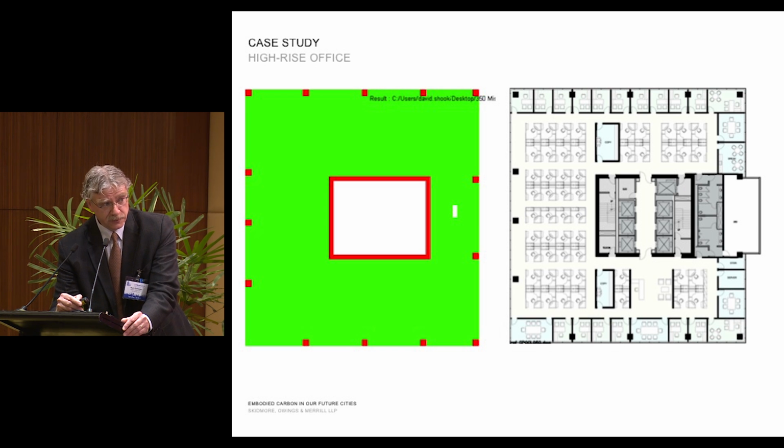It's a core-only building. We optimized the floor, and the red areas that you see are areas of highest demand, and areas in blue are least demand. And we came up with a flat plate system that spans nominally 35 to 40 feet, depending on where you are, with a large cantilever in the corner that faces towards the Transbay project.